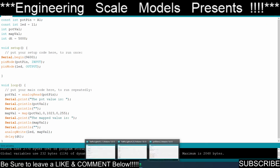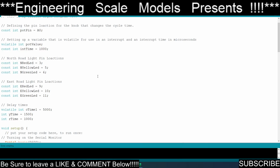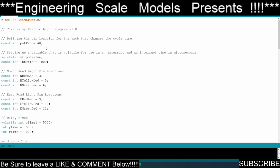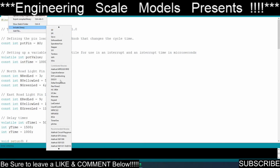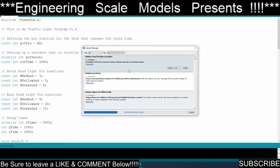Let's pull up this code here. Not that one, this one. This one works better. So this is better to read. So we're going to come up here, and you see I did the hashtag include timer1.h. Now you get that from going to sketch, include library, and then you scroll through your included libraries to see if you have timer1. If you do not have timer1, you go over to tools, manage libraries, click on that, and then you can come in here.